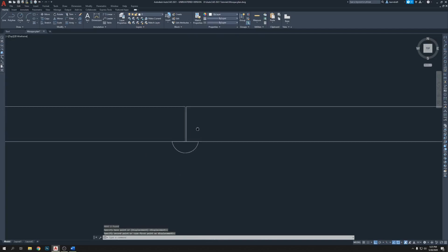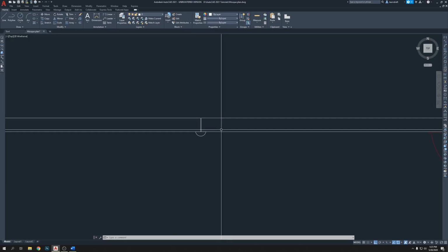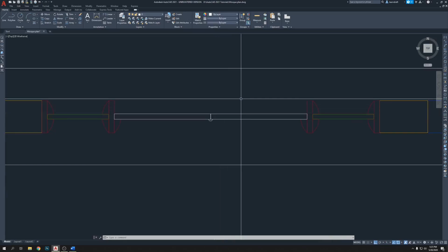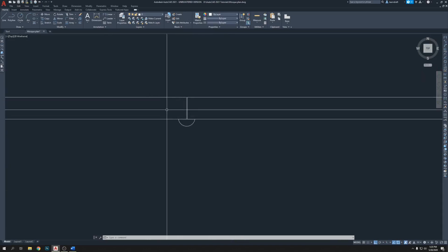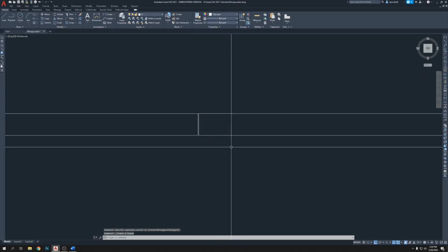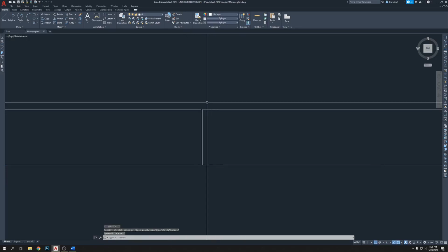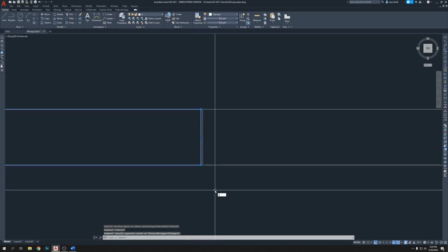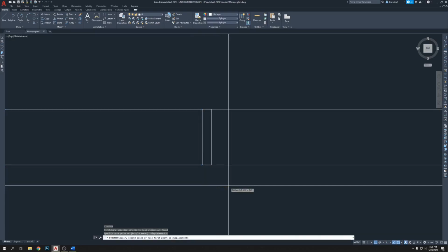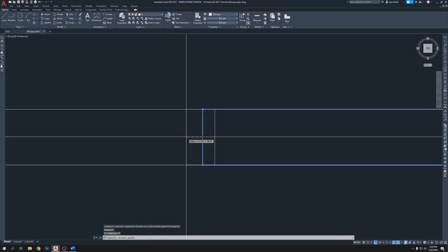There are so many different ways we can do it, but this is the way people normally do it, and it doesn't look good at all. Why are we going to follow them? Let them follow us. So delete this one. Make this frame stretch this way half an inch, 0.5, and then this one goes this way, 0.5.